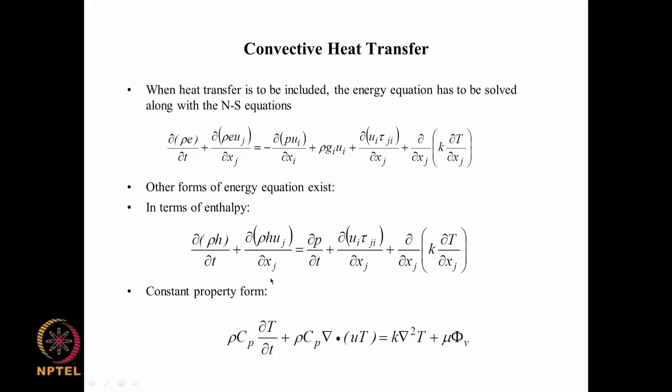And solution of this energy equation along with the other governing equations is sufficient for us to distinguish between convective heat transfer and how much of convective, its Reynolds number dependence, and all those kinds of things we will be able to get by direct solution of these equations without having to worry about Reynolds number effect and all that. Reynolds number is included in the equations. We don't have to bring it out specially in the form of correlation.